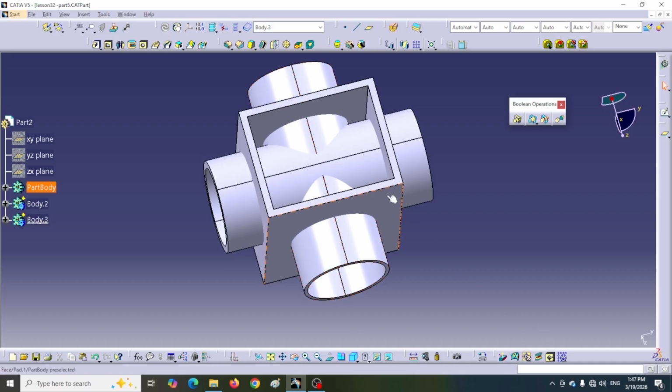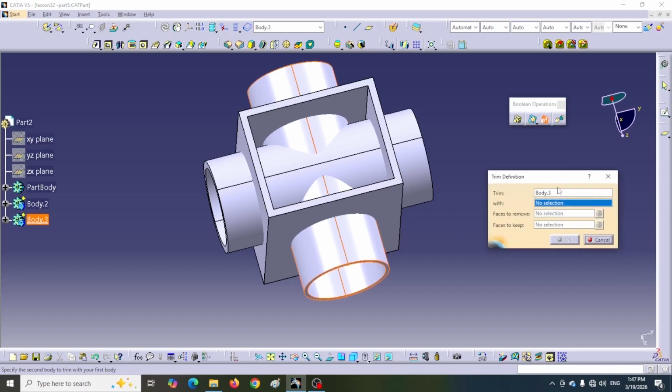First, I want to cut off the bottom of body 3 to the level below the cube and add it to the cube. Now body 3 is active. I click on the tool to activate it. You will see that the settings window did not open. I click on body 3 in the design tree. The tool settings window opened.